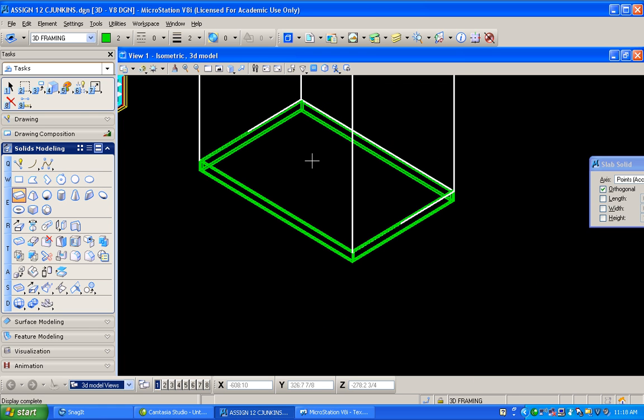So I want to run them 8 feet front to back, so we're going to generally lay our plywood or sheathing on the top of this in, well, I guess it really doesn't matter. We've got 12 feet in the other direction, so we can run our short stringers this way. Now these are on the outside, so we need to put